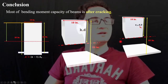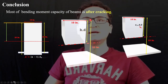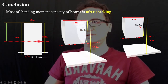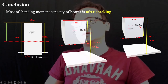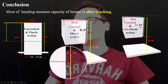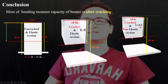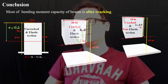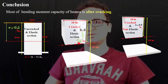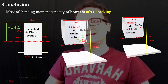At the same time, another interesting result is that most of the bending moment capacity of beams comes after cracking. So the very first scenario has no cracks, we have the entire section, and you can easily see an uncracked and elastic section. We have a cracked and elastic section. We have a cracked and non-elastic section. For the first part, we have 13.2 inches. It decreases to 7.6 and ultimately reaches 4.9 inches in the last scenario.